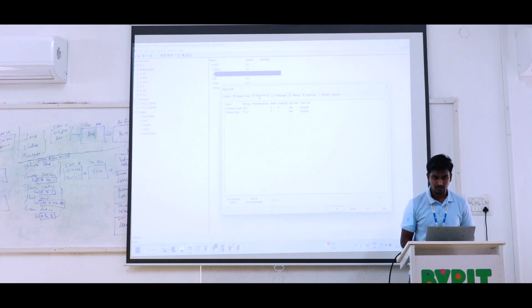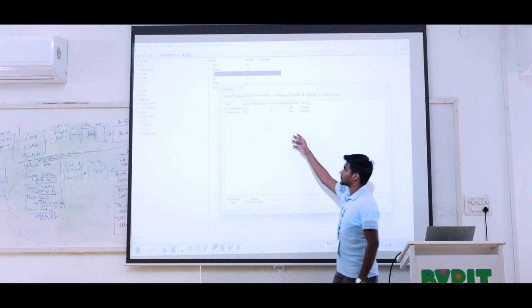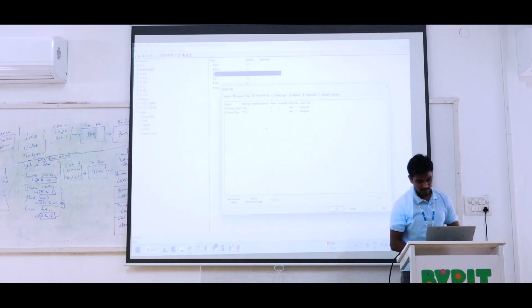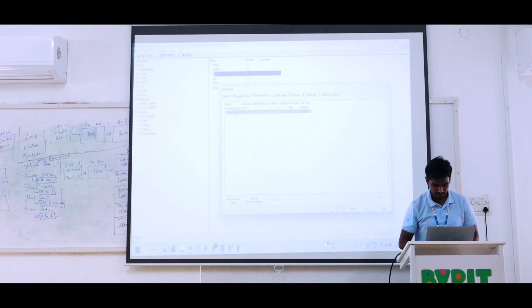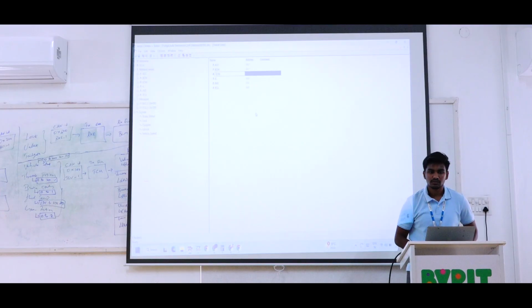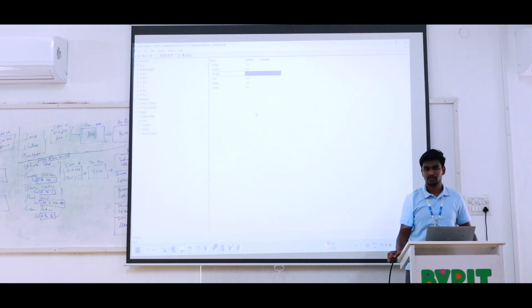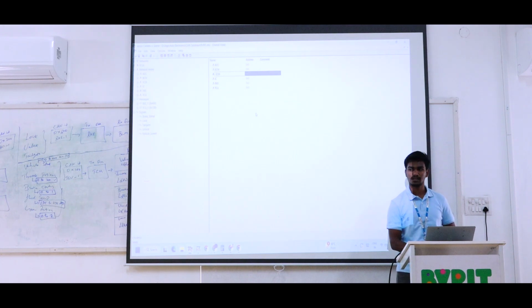Yes. So now the ECM received both vehicle speed and brake status, but we don't want the brake status for this ECM. So what we are going to do is, I just do it again. I remove this mapping. The transmitter is only sending the values, not receiving them, because we are not mapping it as a receiver. But this ECU is able to receive any kind of other signals. If we map them, we can receive other signals also.